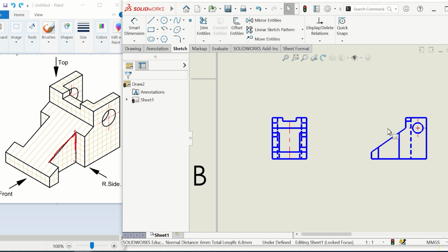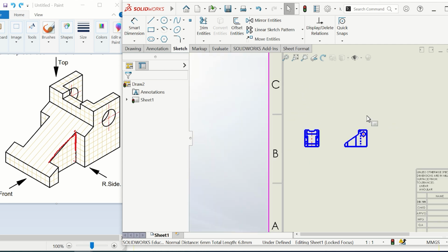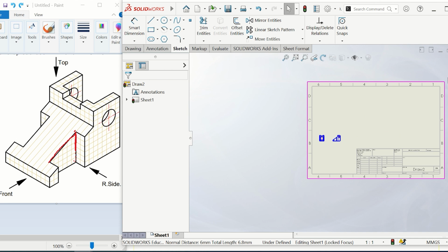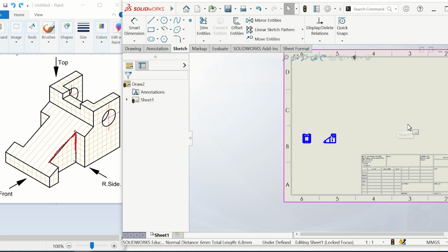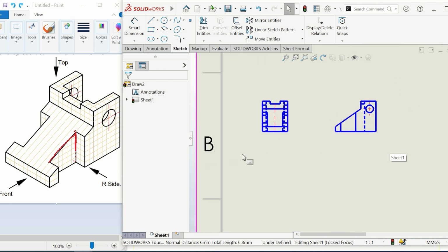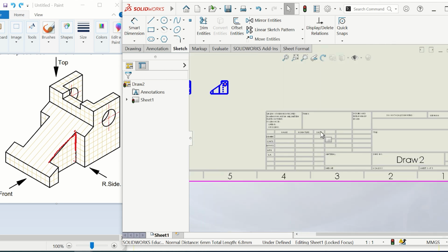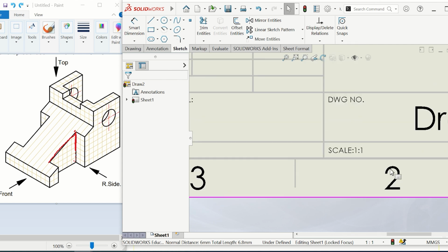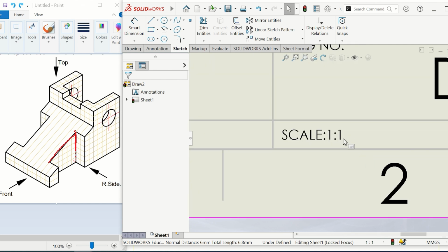Now I'm gonna draw the auxiliary view, and I'm gonna leave the top side view for you to work on by yourselves, okay. The top side, which is going to be somewhere here. By the way, the paper size here turned out to be very small. What we can do at the end, the paper size is very big, we can scale it up. It means I would select everything and let's say scale the drawing, I don't know, 5 times. And then I would have here, let me show you where, here, a scale of 5:1.